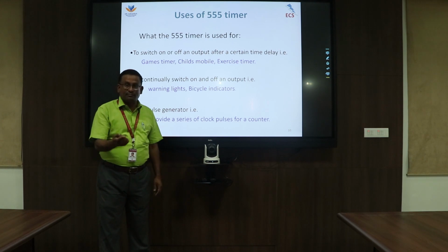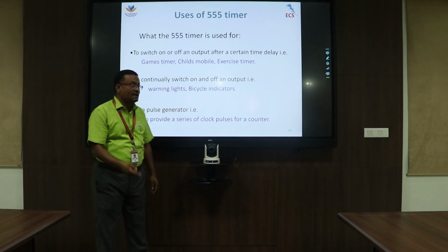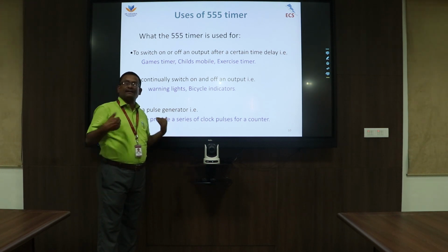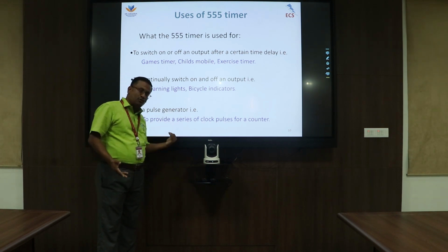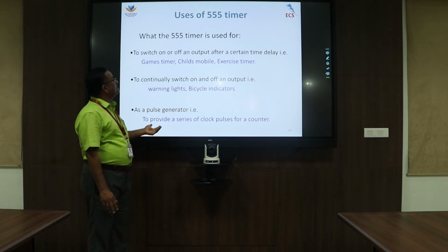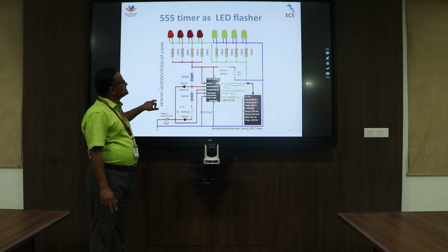For generating the clock pulse, we can use this IC 555 timer as an astable multivibrator, and I can use it as an input clock pulse generator for any kind of circuit. So these are the applications of the IC 555 timer.